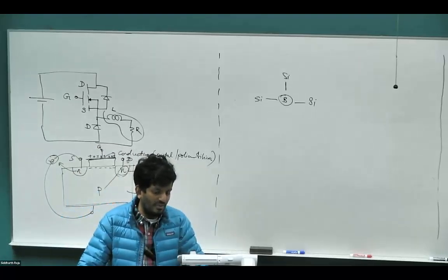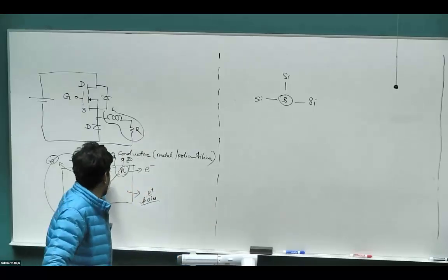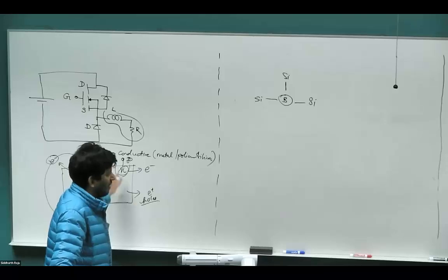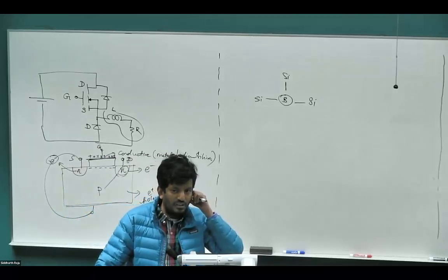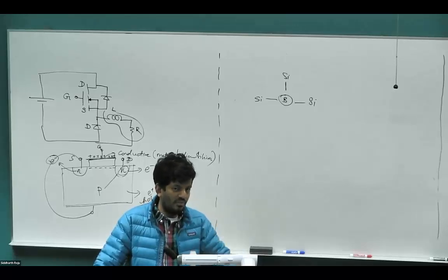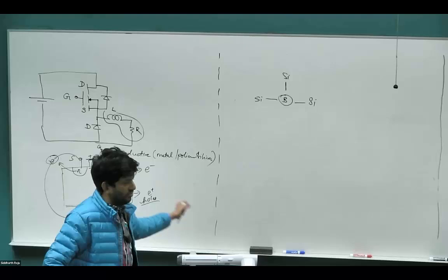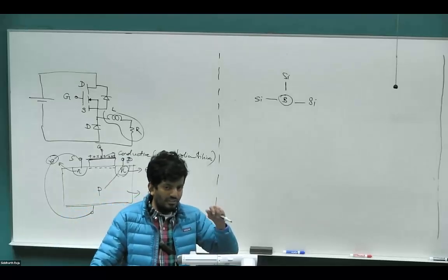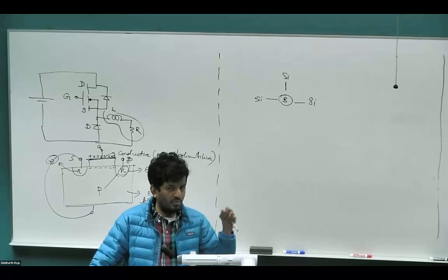So what happened is basically they took, but a BJT has a very good advantage. A MOSFET has a big problem where this channel that has formed here is basically a resistive channel and it drops a lot of voltage. Right? A BJT, on the other hand, there are some principles due to some drift layer injection and so on and so forth, which makes the resistance of the BJT go extremely small. So there was 2 separations. MOSFET used to be used when we have low voltages and low currents. BJT used to be used for very high currents because the resistance of a MOSFET would be too large for high power application.